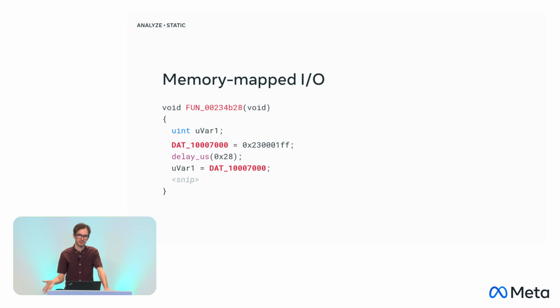This is writing to what's called a register, and a register is what makes up all of these memory-mapped I/O or peripheral regions. So every bit in the register has some meaning to the hardware. And when you write to a bit, you're telling the hardware, hey, enable this interrupt maybe, or save these 8 bytes of the register as an entry in the queue that's going to go out the serial port, or any number of things. Or if you have a board with I/O pins, like a Raspberry Pi, there's a register that says, here's the state of all these pins, and you write to it and the state changes. It turns a pin on or turns the pin off.